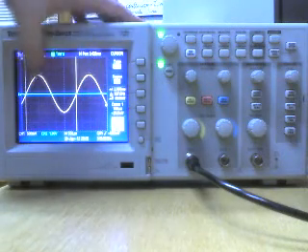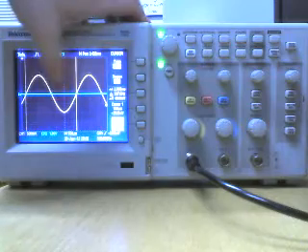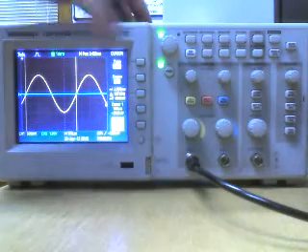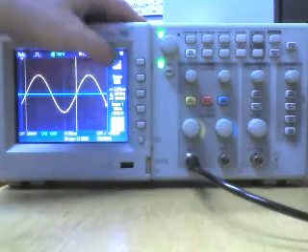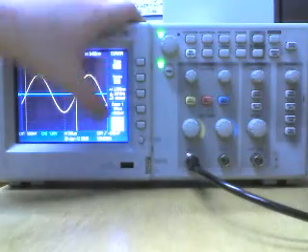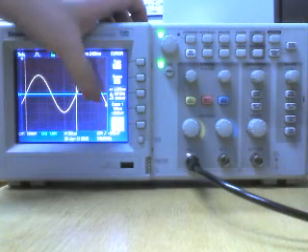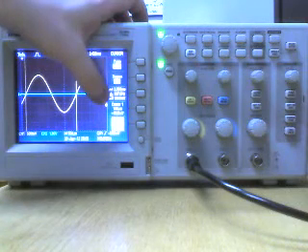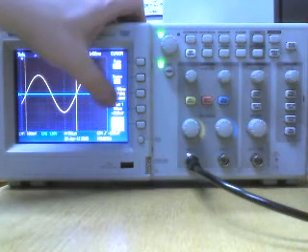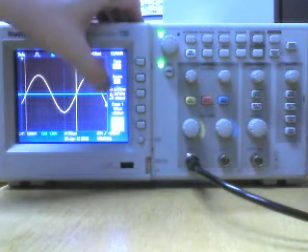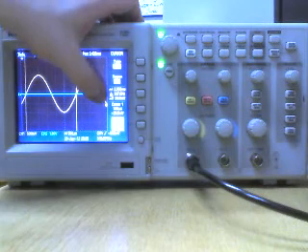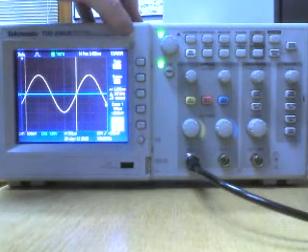The difference between the two cross points, where it's crossing the axes, is about 20 to 40 millivolts. Now, in all these measurements, these auto measurements and cursor measurements, you will always see a fluctuation. So you may want to write down the minimums and maximums, what it's fluctuating around, and these will contribute towards your error in your reading.